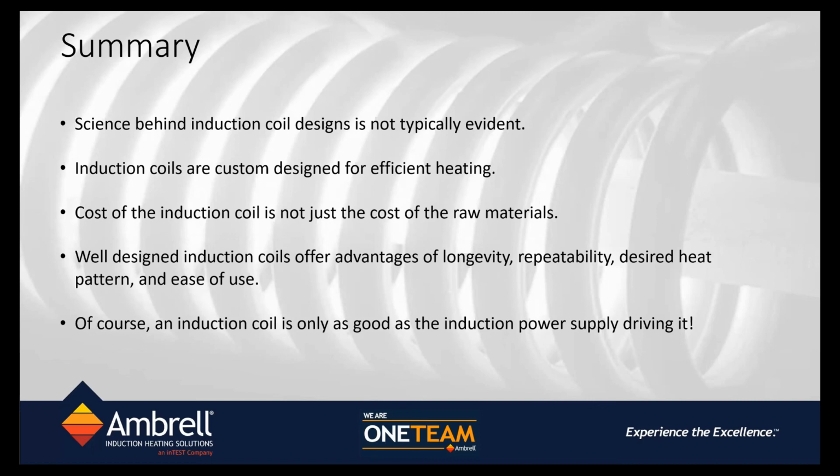So the resistance of the coil is only a function of the temperature of the copper. Because there is water flowing through, the copper is never getting hot. The part is getting hot, and its electrical resistance is increasing. So there are charts, people have done these types of tests, and you can find the data in literature of electrical resistance of different metals at different temperatures. So that's where I would point you to get the electrical resistance.